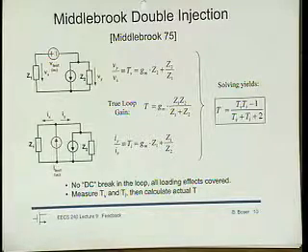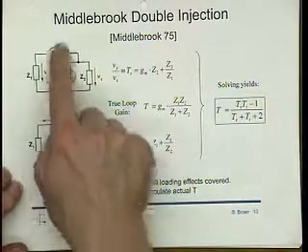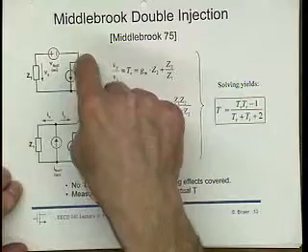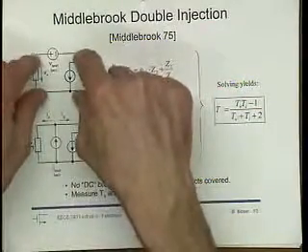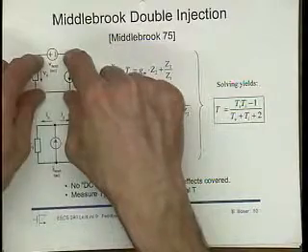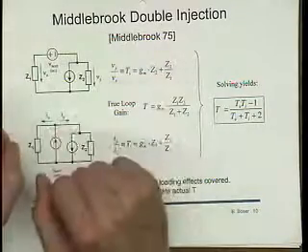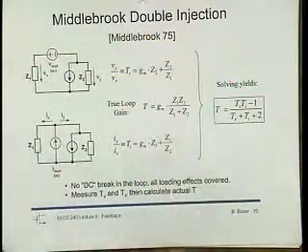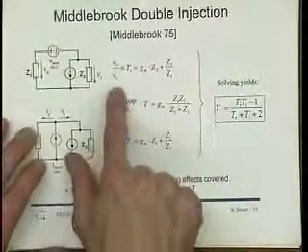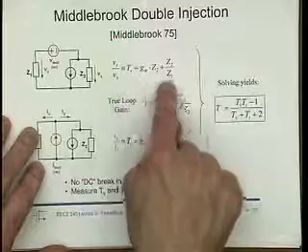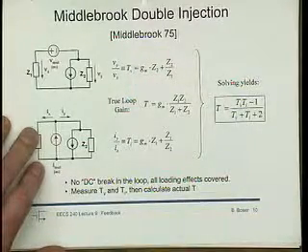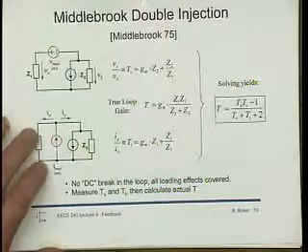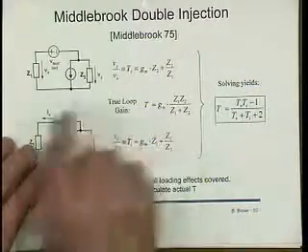But now we run an AC analysis, and we look at the voltages that appear on the two terminals of this voltage source to ground. We figure those out, and then it's a little bit of math to show that this voltage ratio is related to GM and these impedances. We call that ratio TV.